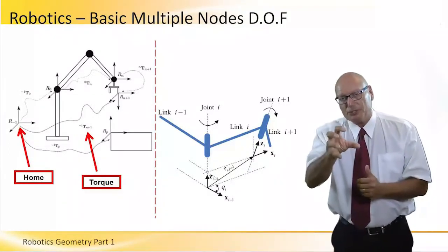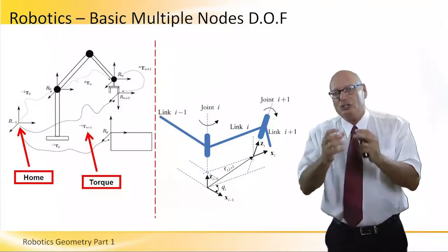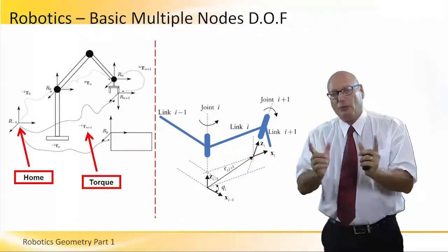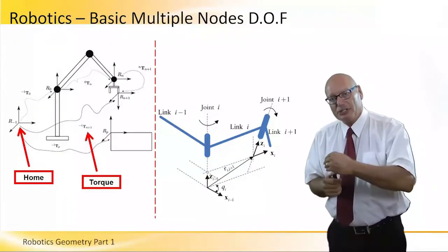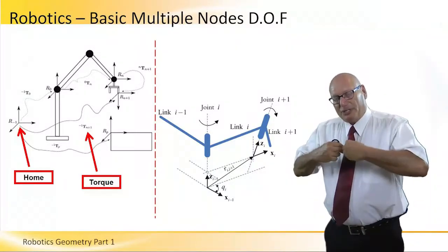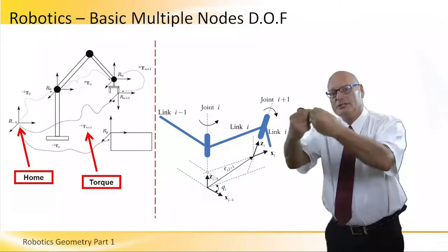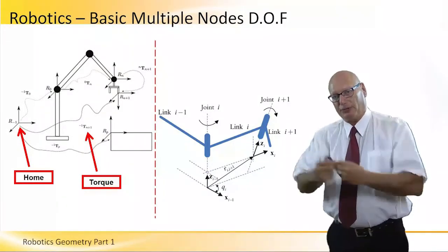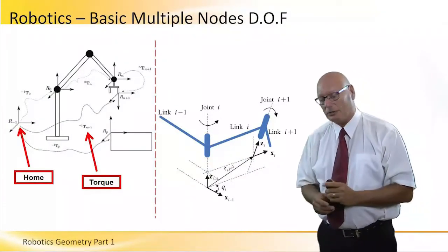And that particular object has its own physical characteristics, which will change the behavior of the fingers, will change the behavior of the center of gravity, will change the torque associated with the gripper itself. So first of all is the source of the gripper, XYZ, and then the tip of the gripper has its own XYZ because of that particular object that it's holding.